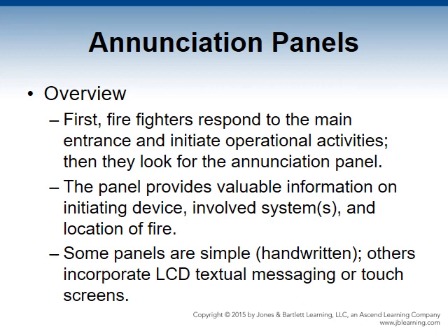Annunciation panels. After responding to the main entrance and initiating operation activities, firefighters look for the annunciation panel. This notification or indication device provides valuable information, such as the initiating device, the systems involved, or the area of the building where the fire is located. Some panels are simple with handwritten information, while others have LCD textual messaging or touchscreen computer technology to relay information to the firefighters.